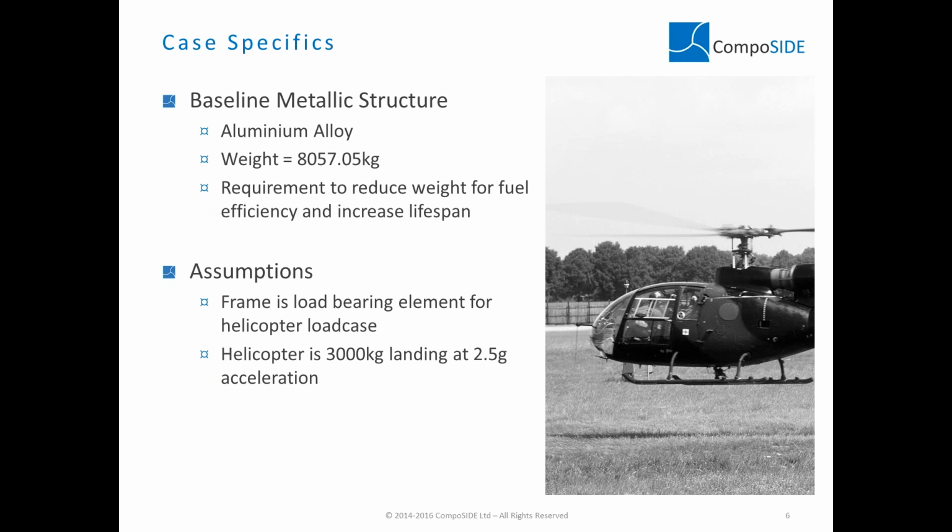We're going to make a few assumptions. So the loading in the frame is going to be 100% taken from the helicopter, and the helicopter is going to weigh about 3,000 kilograms, landing at a 2.5 G acceleration, so a pretty heavy impact case.